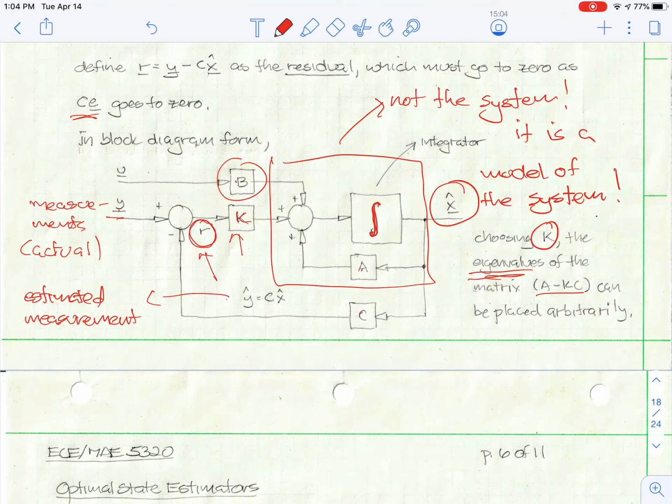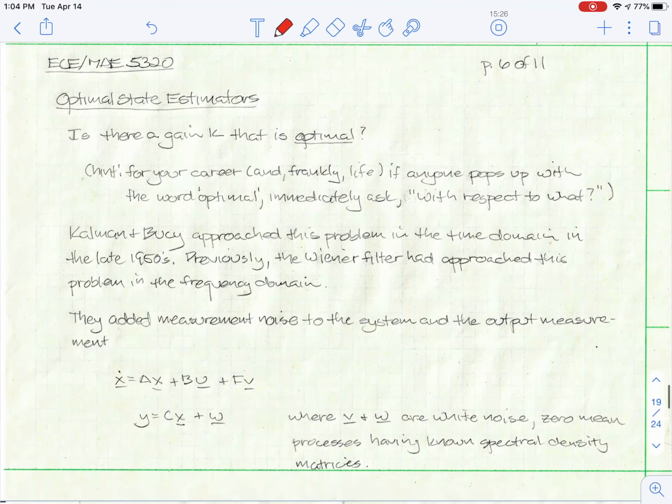These are fixed values. And so I'm basically saying that is the model of my system. So Kalman filters have a habit of diverging if your models get too far separated. And divergence in a Kalman system is bad because if it diverges, that means your estimates diverge. If your estimates diverge, you can drive the system unstable.